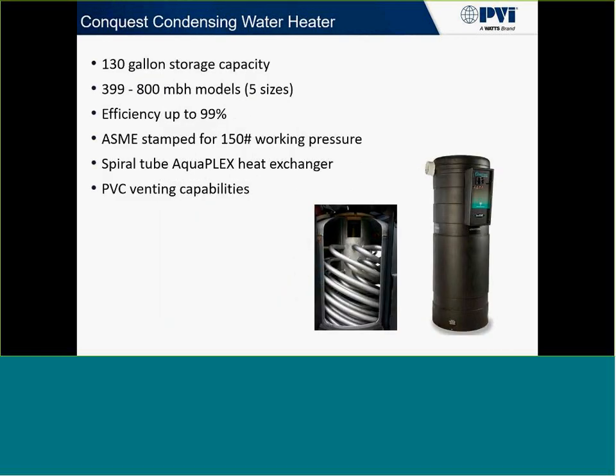Now on the larger tanks, the 130-gallon tanks, it's more of a spiral type heat exchanger design. It's still a single pass, which is very important when it comes to the acoustics of it. And the reason why is because certain manufacturers have more of a baffling type setup where they have vertical fire tubes, but they redirect that heat and that flue 3 different times in order to scrub as much heat off of it as possible.